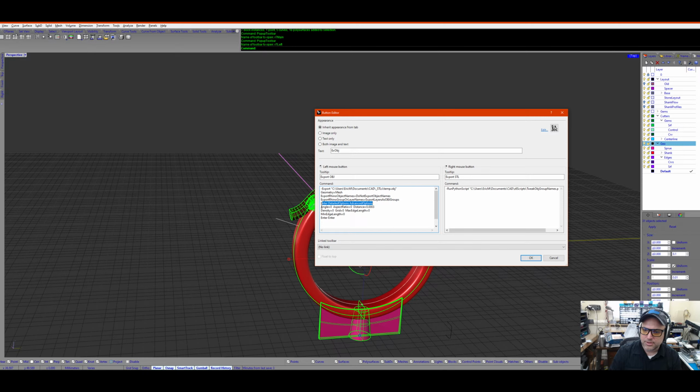Detailed options, advanced options. This is my mesh settings. I've just found that these are a good setting, and basically everything's 0 except distance from surface. So I've got 0.003 there. It will give me a very large mesh. It'll be probably in the 150 meg range. It's got plenty of detail.